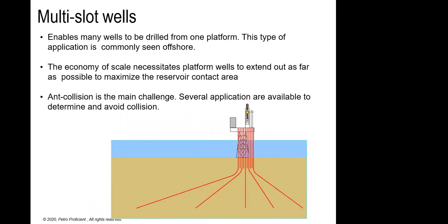Now, this is an offshore well where you have a slot, and from there you drill from the platform. You have a platform rig, and you drill multiple wells from the same platform. In shallow waters, this is a very common practice in offshore drilling, where you have a platform and one template from where you drill multiple wells. There also you need directional drilling, obviously, because you need to drill in different directions. You cannot drill in the same direction.